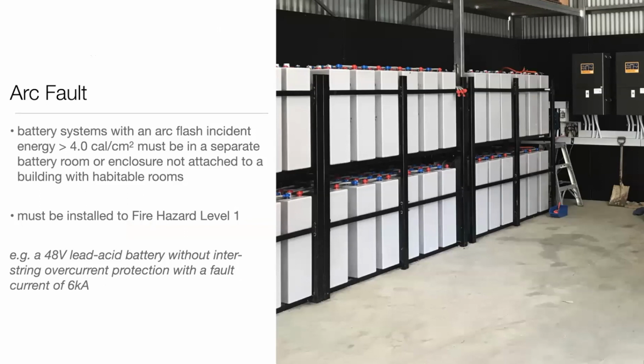Here's an example of a large battery system. It's actually something that my company installed some time ago for a customer. This isn't finished. This is a construction photo. Probably you can see some of the terminals are still hanging off. If a system like this was over 4 cal per square centimetre, which this would be if we didn't have string overcurrent protection, it couldn't be installed in a building with habitable rooms attached.